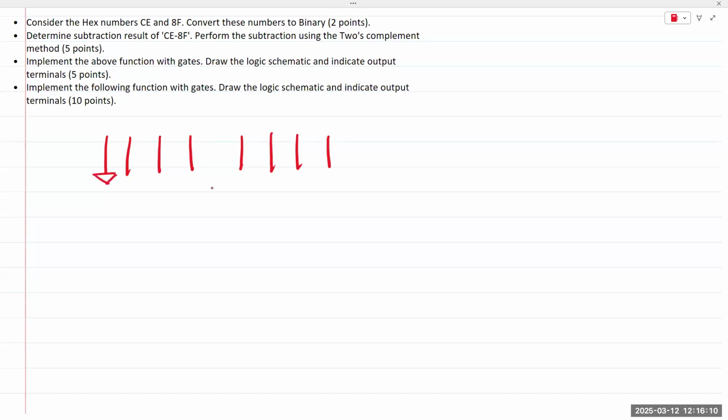You'd simply take the wire, you'd have an array of NOT gates. And that would give you your ones complement. So here's the hex number. Now you got 4 bits, 4 wires, could be 0, 0, 0, 0 or 1, 1, 1, 1. But if you pass it through a NOT gate, it gives you the ones complement.